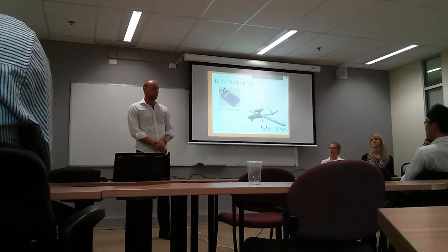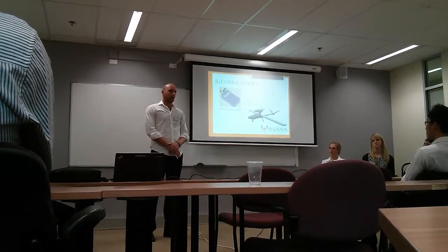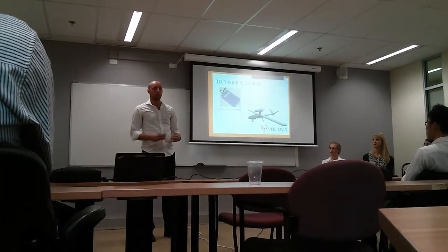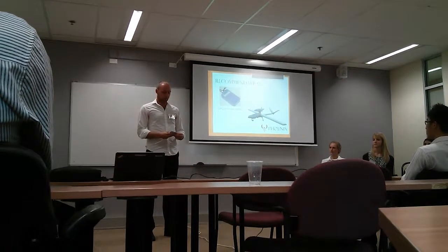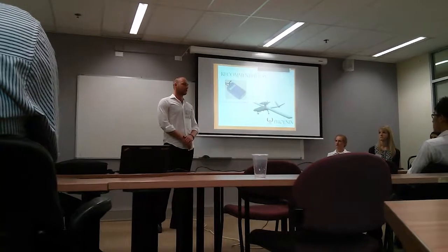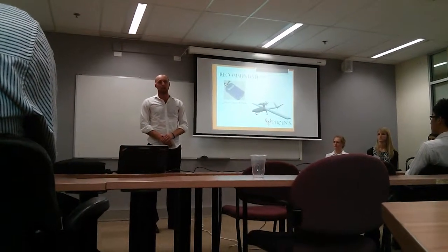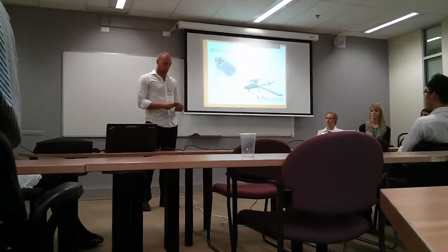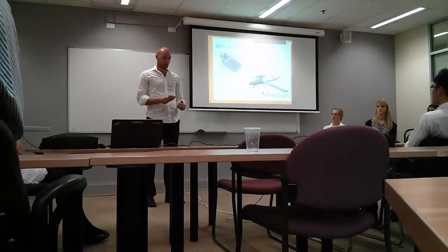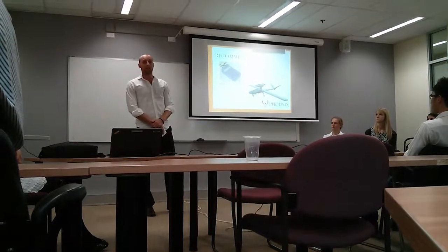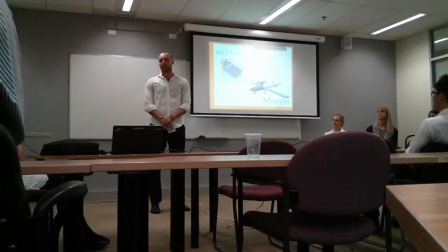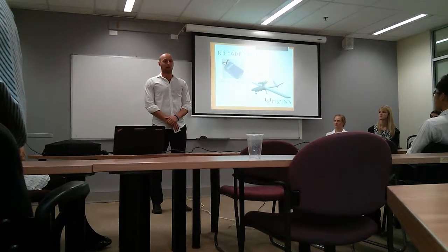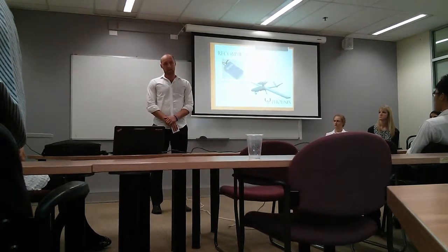After preliminary investigation of existing technologies, it has been found that a UAV in the magnitude of a 12-foot wingspan, flying within the CASA regulation at 133 meters in the air, utilizing an infrared camera with a field of view of 90 degrees, which is fairly moderate, maintaining its altitude via LiDAR, traveling at a modest 80 kilometers per hour, once it gains altitude, would be capable of performing a sweep of a 250 meter by 5 kilometer fire front in 3 minutes 45 seconds.